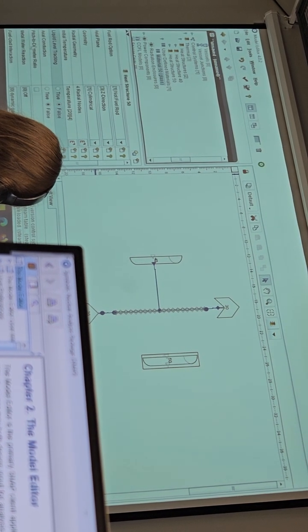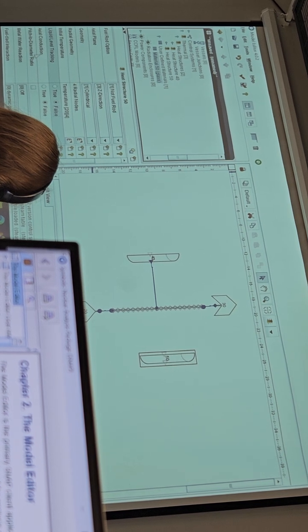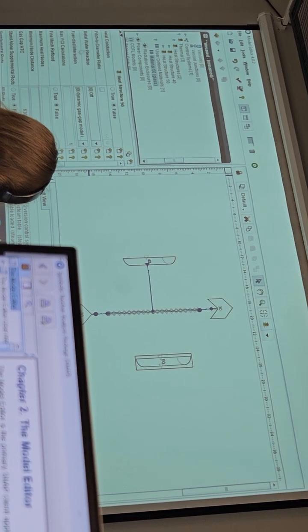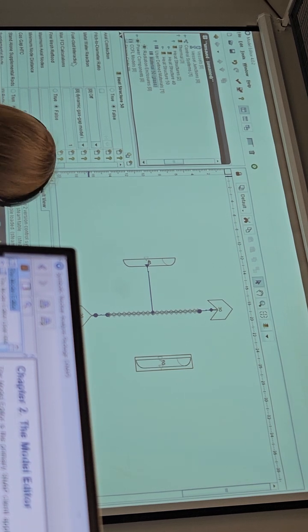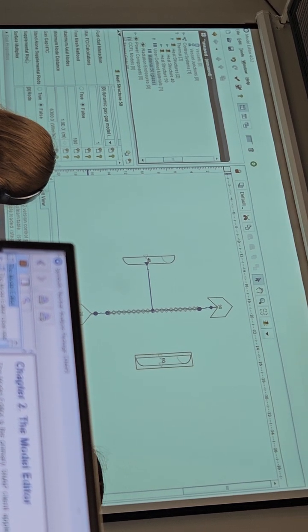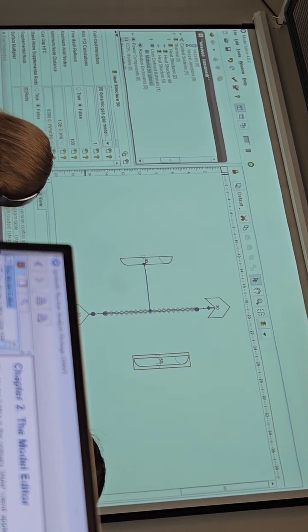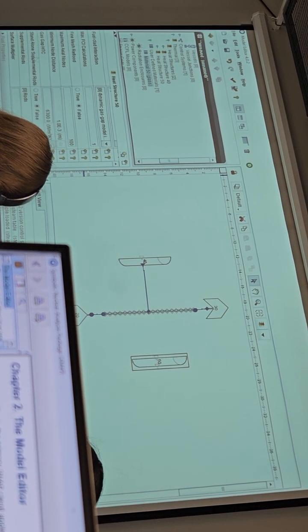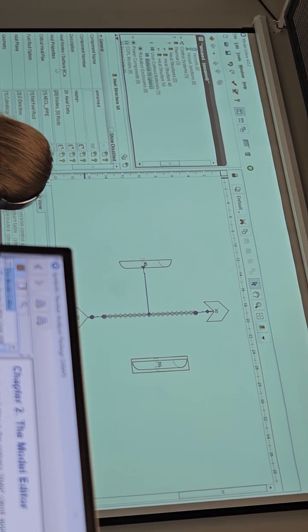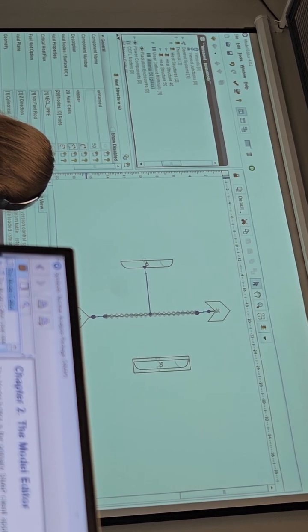We don't need the axial conduction in this case since the thickness is just 3 millimeters. So we don't take it into account, just to reduce the computational power. Fine mesh flux, we don't need that. So we don't have any gas gaps to define the heat transfer coefficient. Only one thing is that we have to define the outer boundary condition.